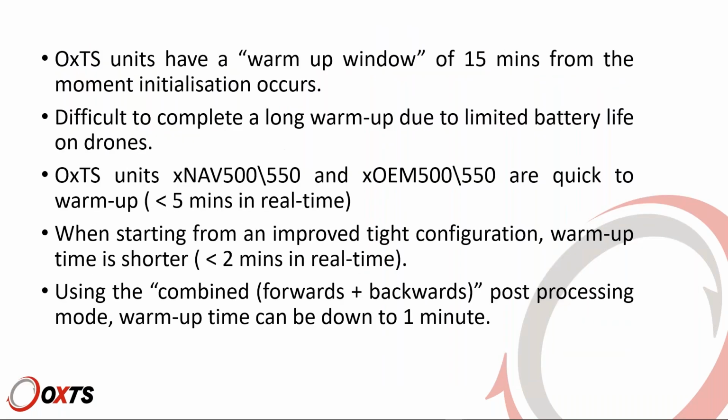The warm-up procedure. The first thing to say is that you've got a warm-up window of 15 minutes from initialization. That's not from when the system is switched on, that's from when the system initializes. 15 minutes during which the system is in listening mode, so to say. So it's open to learn about the surrounding environment and understand what its real orientation is, how distant antennas really are. So you need to complete the warm-up maneuvers, and we will go through this in a second, within 15 minutes from initialization. After that, the system will be way less open-minded.